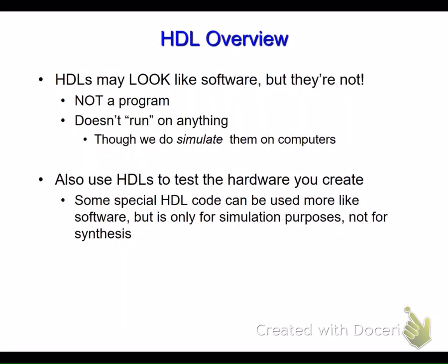Again, I would like to emphasize that these might look like software, but unfortunately they are not. They are not a program and can't run on anything, meaning the code might not be synthesizable. It can be good in the simulation, but unfortunately after synthesis, it won't work. I will give examples for that.